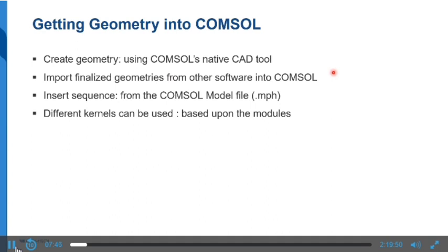That is also possible. But the difference between point 1 and point 2 is that whenever you are importing finalized geometry from other software into COMSOL, you do not get access to all the steps used to build that geometry in the other software. Whereas when you are creating the geometry in COMSOL, definitely you get access to all the steps. So here just the finalized geometry will be imported.